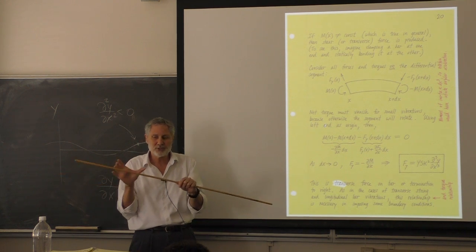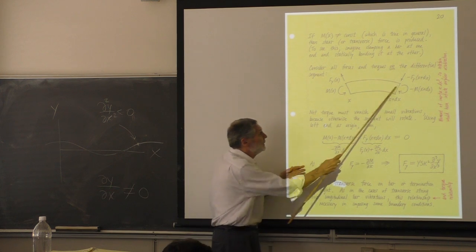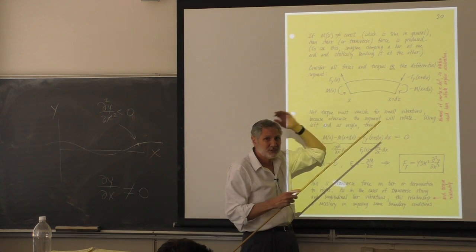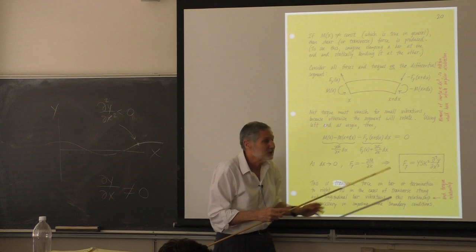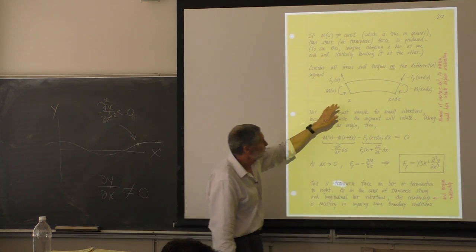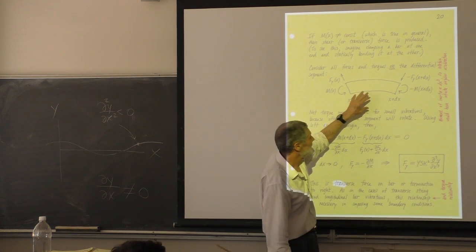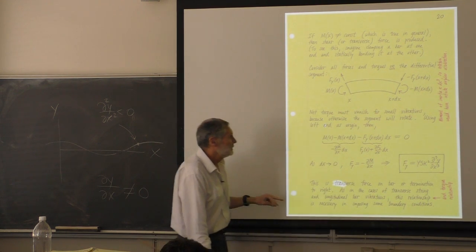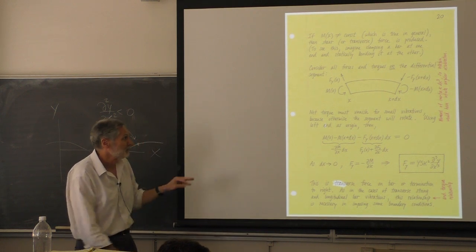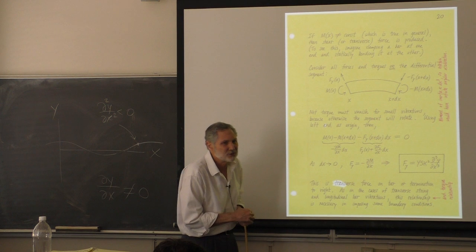Because the moment of inertia is going down quickly, right? It depends upon the square of the length here, the moment of inertia. Remember Newton's second law for rotational motion? The torque is the moment of inertia times the angular acceleration. So it's going down quickly here. I made a specific comment there. So if the torque doesn't vanish in the limit as this shrinks to 0, you're going to get infinite angular acceleration. So that's the trick here.